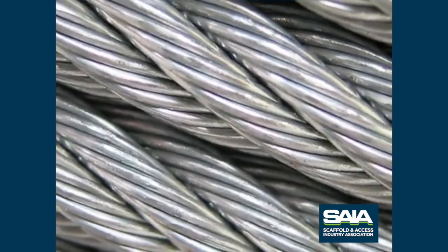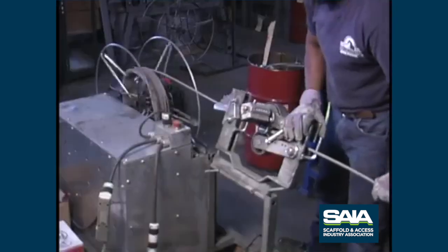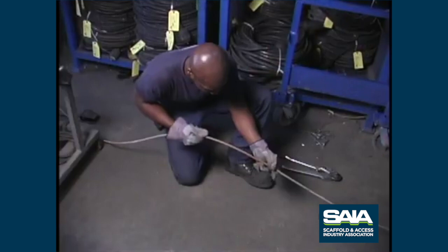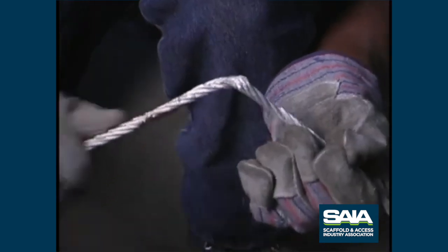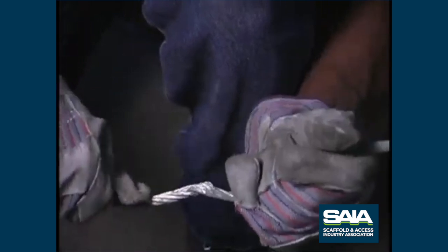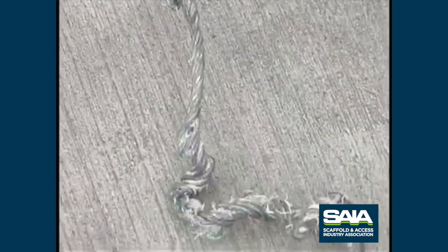Proper rope handling and maintenance are critical for safety. Inspect the rope before putting into use. Check for wear, broken wires, kinks, burns, bird cages, corrosion, and chemical attack. Pad ropes that contact any surface to prevent abrasion damage.